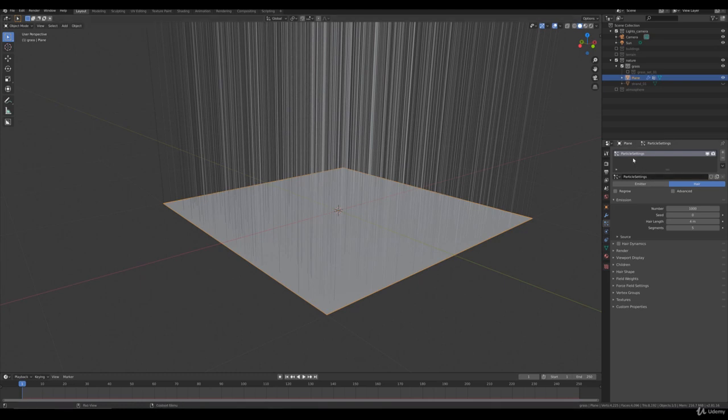I know how to do it, but first I like to change the name and call this grass simple. Default is simple, but this is not really advanced. It's just the most common grass there is. So grass_simple, right? We want advanced because we want all the sliders we need, and it adds the rotation tab. So we will lower this to 70, but let's keep 1000 to show you what happens if we add our strands. So go to render, and by default it's render as path.